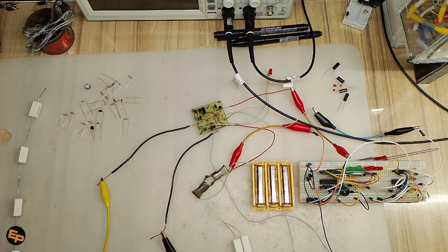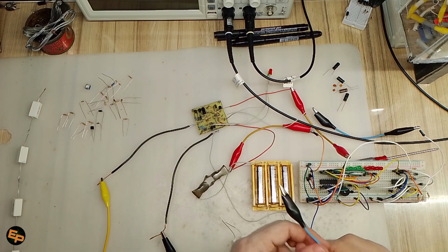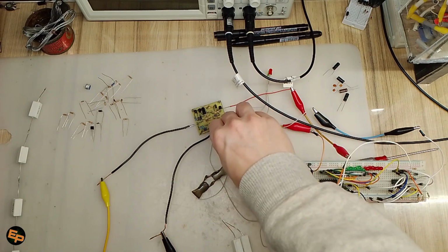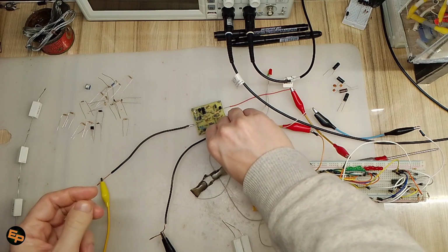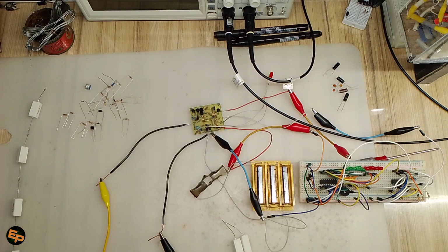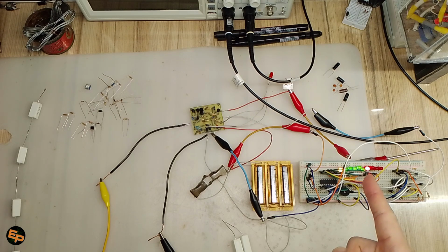Okay, and when I took a much shorter and thicker cable and I connected these two grounds more directly, essentially bypassing that long and thin ground wire, when I was connecting exactly the same thing on the outside, I was only getting 6 LEDs turned on and the other 4 were remaining turned off.